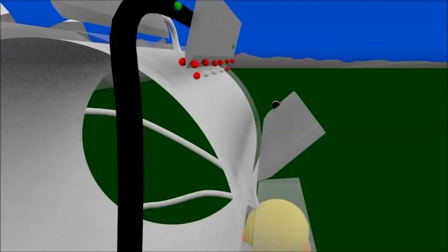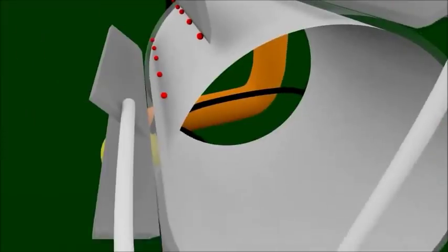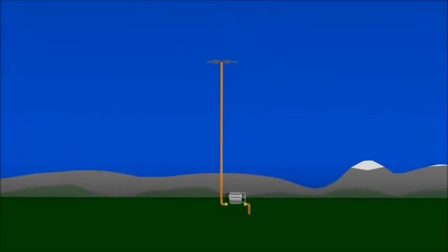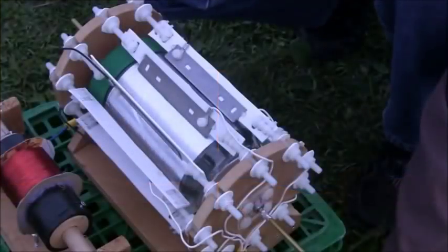Negative charge is then pulled from the plastic cylinder through a gap between the edge of the blade and the cylinder. That leaves the cylinder with the same charge, and since like charges repel, a repulsion occurs that rotates the cylinder. The next blade is connected to earth ground and becomes negatively charged, and since opposite charges attract, it attracts the charged area of the cylinder. It then neutralizes that charged area by taking electrons from the ground. And that's how atmospheric electricity can power an electrostatic motor like a Corona motor.